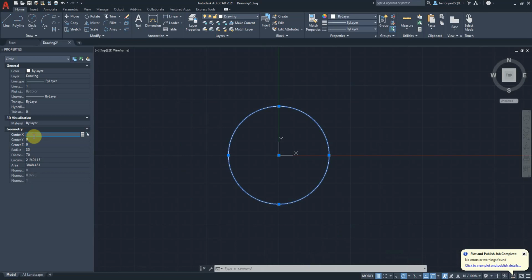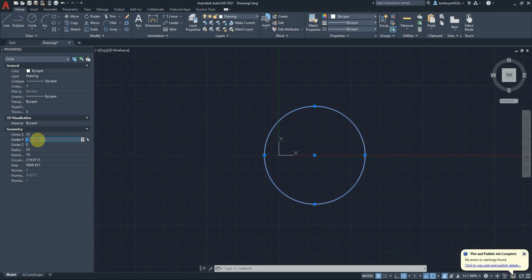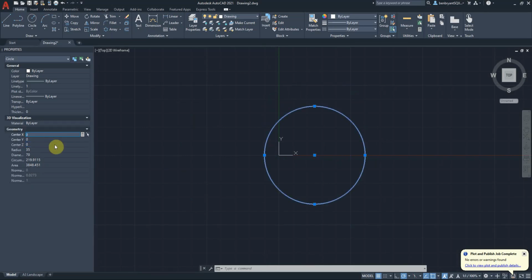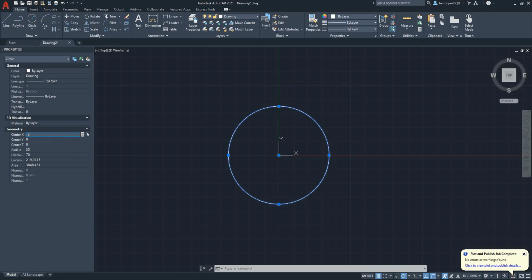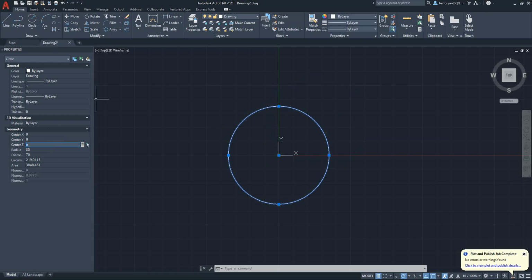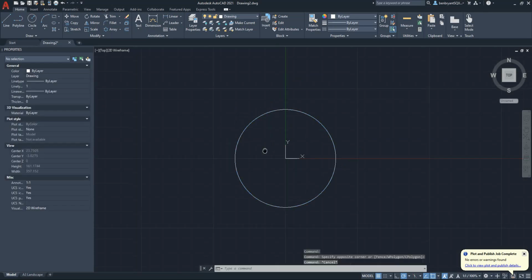Likewise, if you put something in the wrong location, I can move it by putting in new coordinates from wherever it's currently based. I could do 25 by 25. You can also do it vice versa. You can put in minus 12, wherever you want to go. It'll move it around like a normal coordinate system would. So a very useful tool to have.